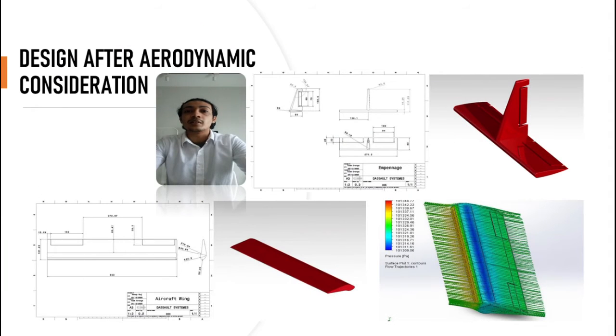Right, thank you Hanif for explaining why we're using NACA 4412 for our aircraft. And here's the main wing design and the detailed shape design. The main wing is attached below the structure of the fuselage, and we're using a dihedral angle design. One of the reasons is to improve the performance of the aircraft to return to the original wings-level condition in windy conditions. Also to produce a negative rolling moment to stabilize the aircraft in bad conditions, and we have done some analysis and we get an efficiency of up to 0.713.